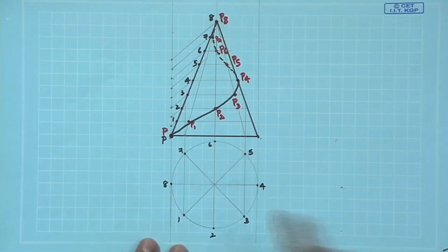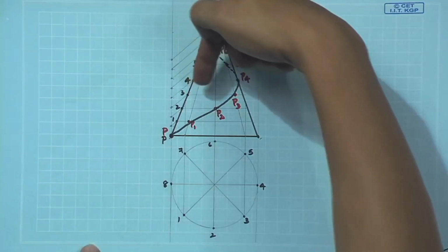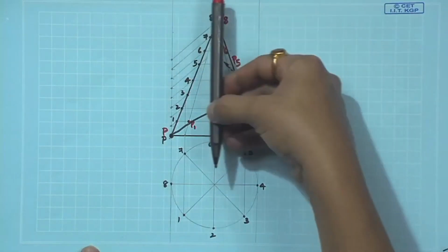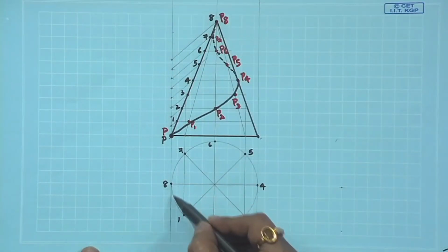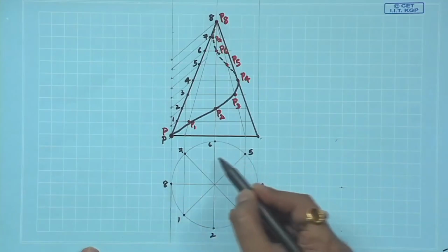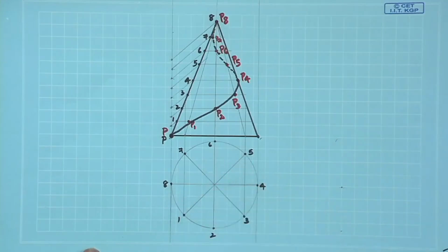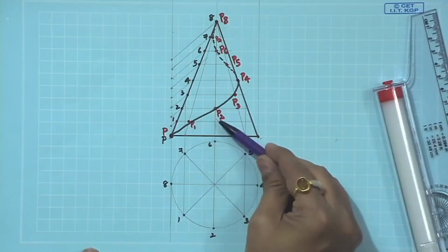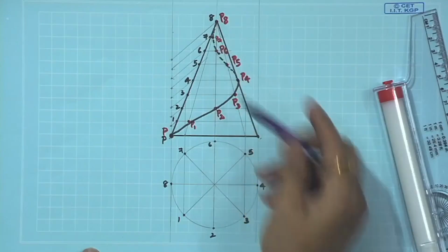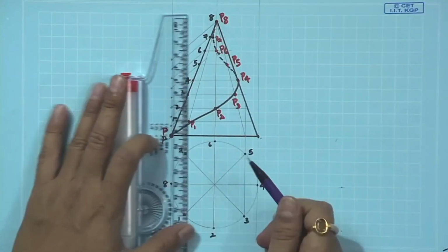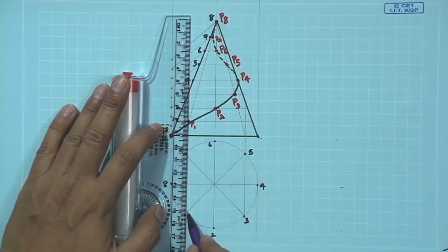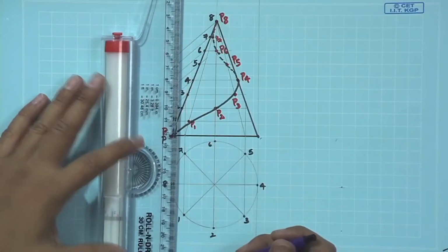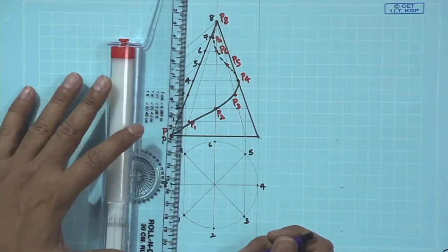So, let us do that for the bottom part of that curve also. From the top view, if we are looking in this direction, how does that helix wind on that plane? Let us draw that. The intersection points are at P1, P2, P3, P4 and so on. The projections we are going to get here go via these bottommost points.